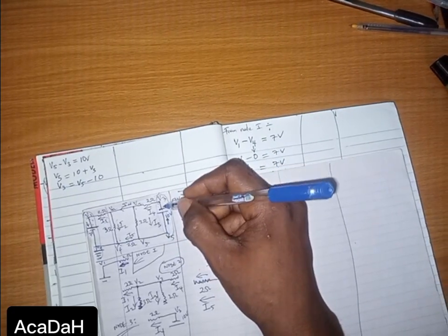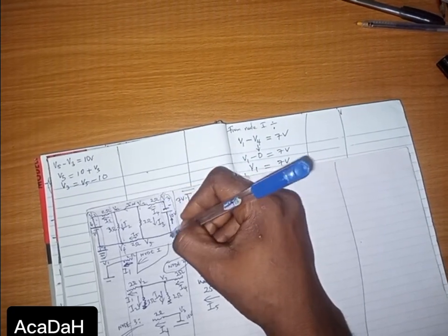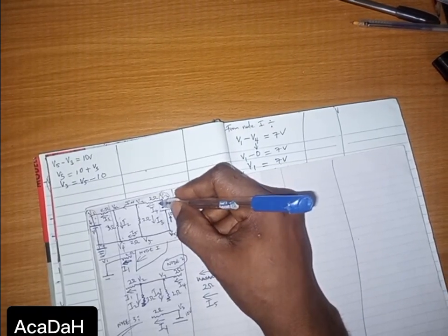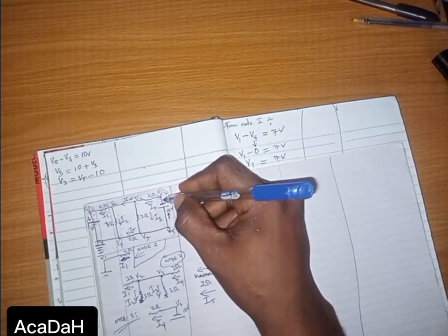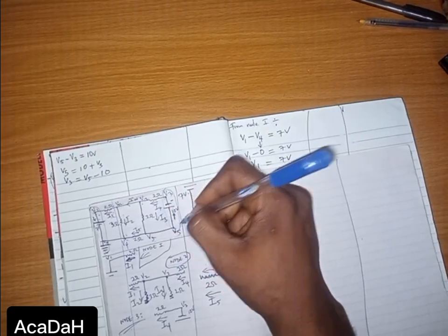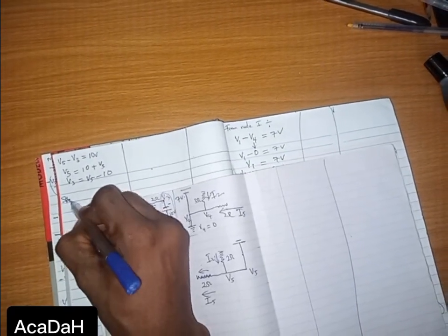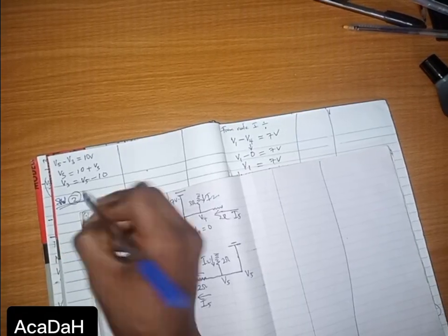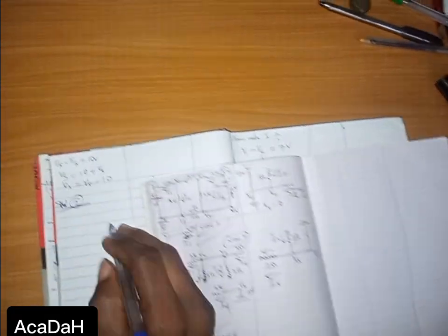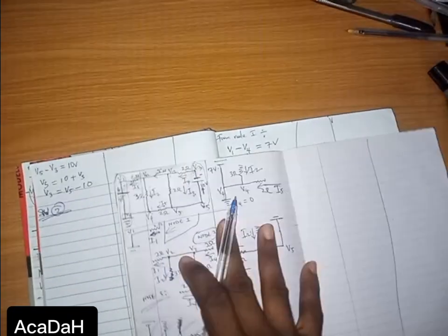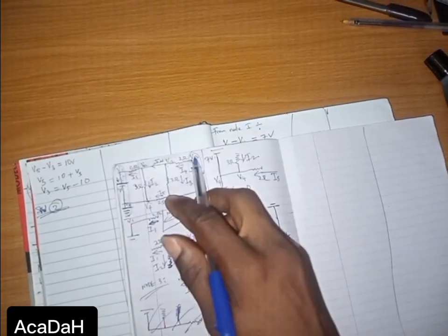So not open circuit, you short circuit it. If you short circuit everything here, remove this voltage, remove this, it becomes a wire. What currents do you have leaving this area, and what currents do you have entering it? You can see very well that for the second supernode, SN2, the currents entering are the same thing as saying go to node 3 and node 5.